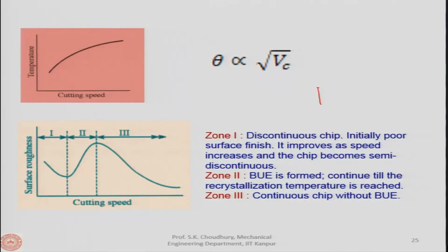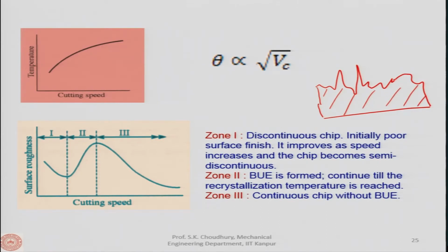As you understand, 1 by surface roughness is surface finish, meaning the more the surface roughness, the rougher is the surface, and the surface finish is low, okay, and vice versa. By undulation I mean that if we look at the surface and exaggerate it, it can actually look like this, all right. So, let us say this is the metal surface. If you exaggerate, this will be the undulation, okay. So, more the undulations, more will be the roughness and less will be the surface finish.